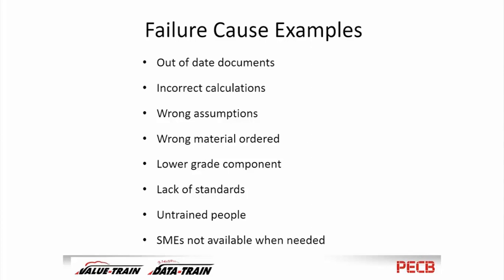And one of the things in their software was an FMEA module to do all the things that I'm going to show you here. I had another piece of software for them to use to do this FMEA. They said, no, we won't use that. We're going to use our own since we do it anyway. So remember, we come up with three numbers and we're going to multiply them together. That's all. It turned out that the people who didn't use their software got the right answer. And this high-tech consulting systems design company got the wrong answer.